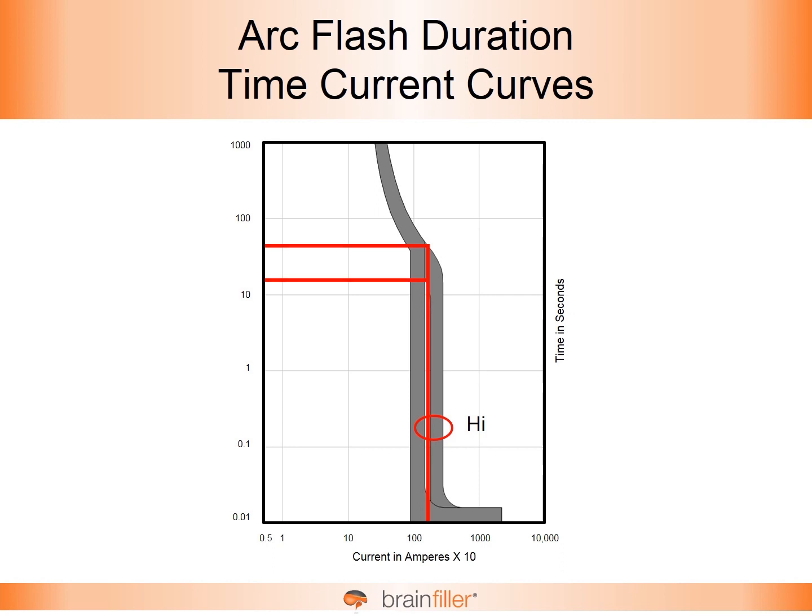Now, realistically, would it take that long to operate? Probably not, but there's no way to know for sure. Would it self-extinguish? There's a pretty good chance that it would self-extinguish. And IEEE 1584 actually has language that if there's room for escape, if judgment is made, you could cap this time at 2 seconds.